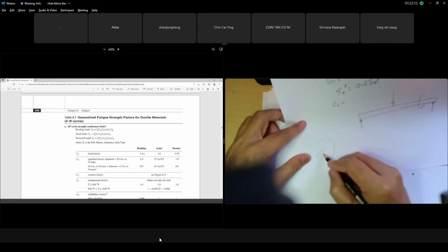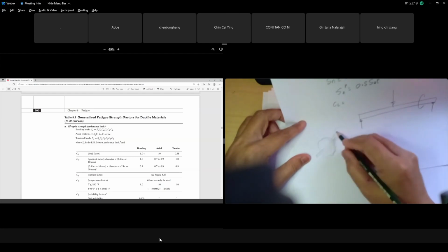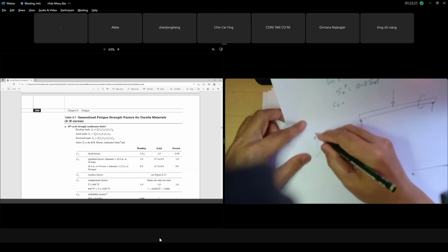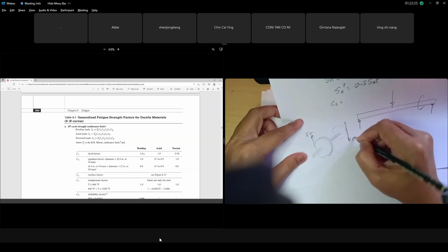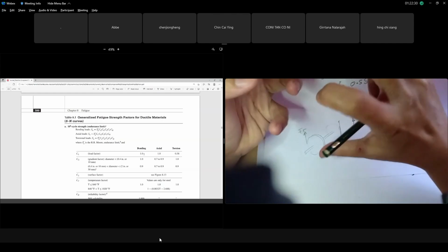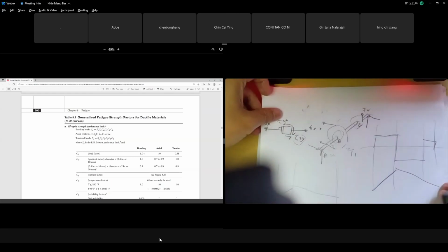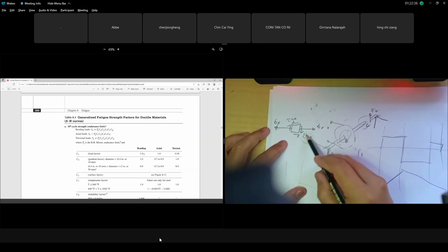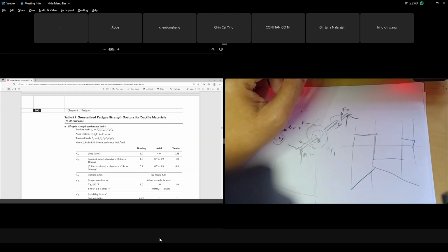That kind of system of your machine, they use another pulley or system. I don't know. They use a lot of tangential force, and the tangential force is bigger. This goes in this direction to twist or something. Maybe that special machine, the torque is much bigger than the bending. Be careful about it. If the torsional stress is bigger than the bending stress, you cannot use bending. You go for torsion.